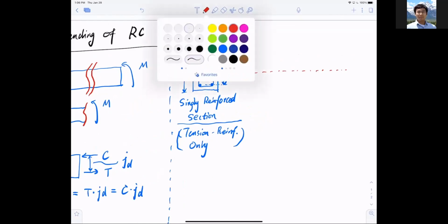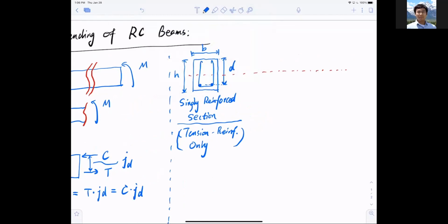Of course, now doing so, 0 point, right? So if you have a strain on the top of the fiber at failure, this is always going to be epsilon cu, and knowing that this number is 0.003. And then I draw the section right here and extending the bottom line here, and knowing that this neutral axis, recall the definition of a neutral axis, meaning no strain, zero strain, right?